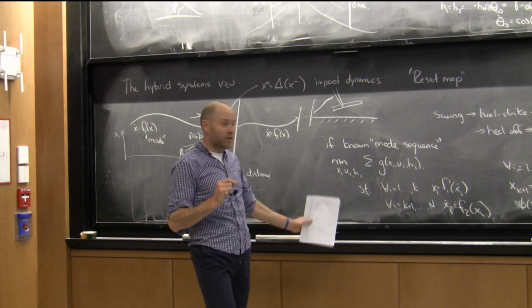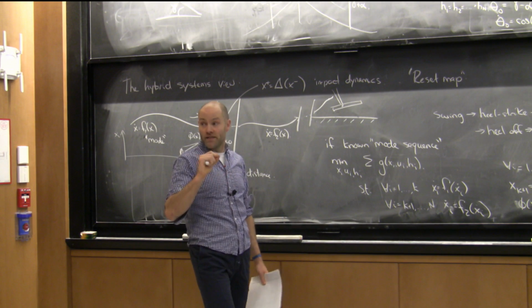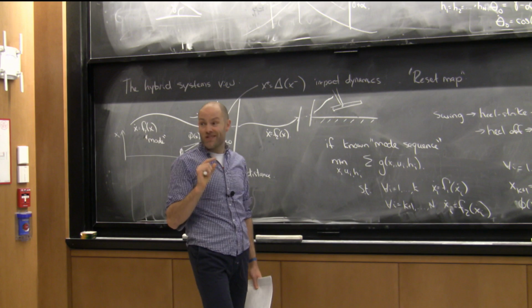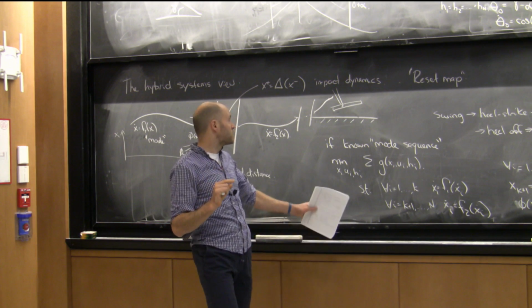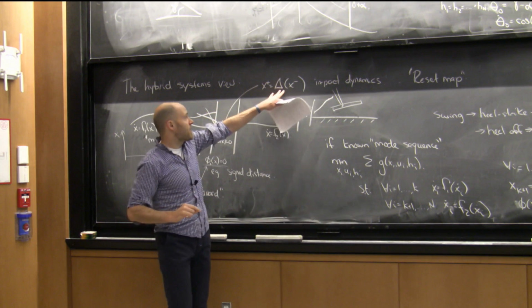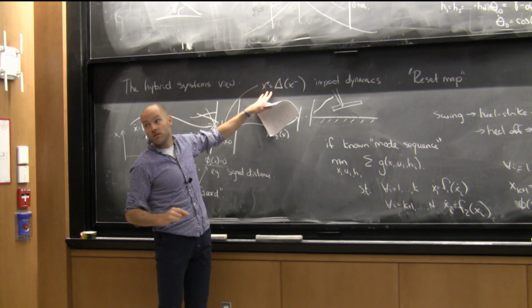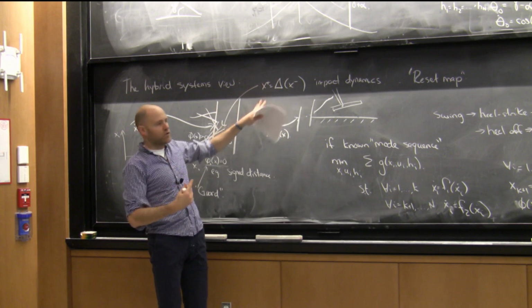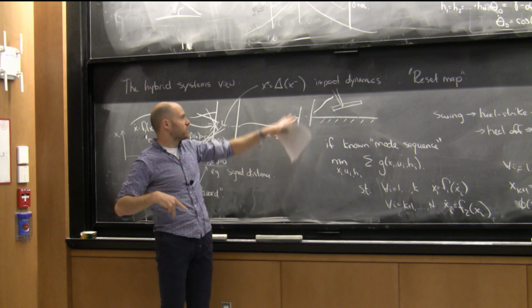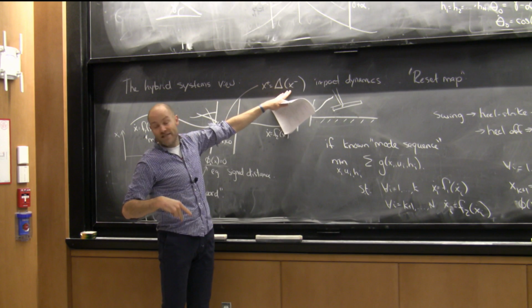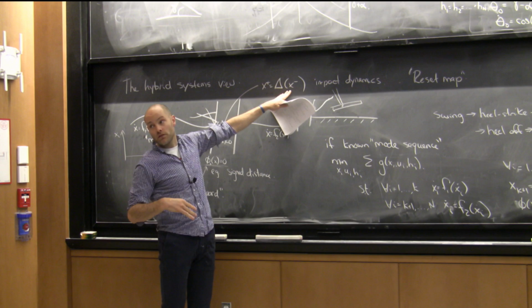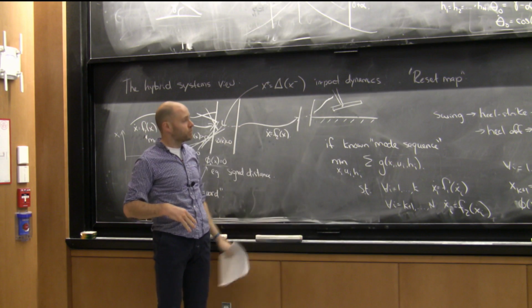And then K plus 1 in this case is T collision plus, the same instant in time. The positions actually have to be the same. For physical impacts, the reset map has the position variables staying the same, unless you do something like reset the angle of your rimless wheel. It's just an instantaneous change in velocity for mechanical collisions. Good question.